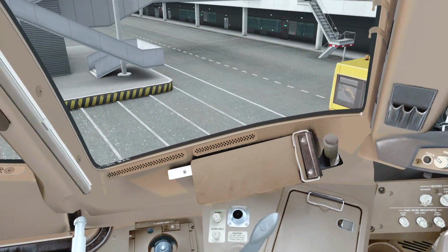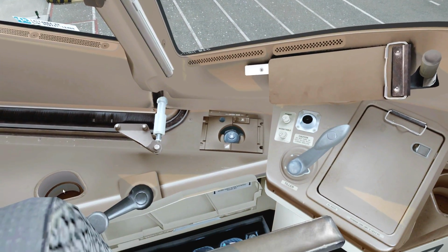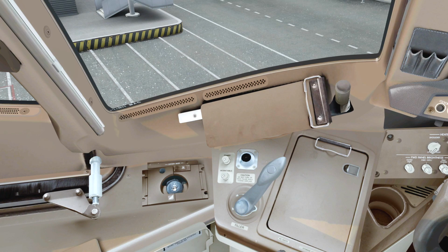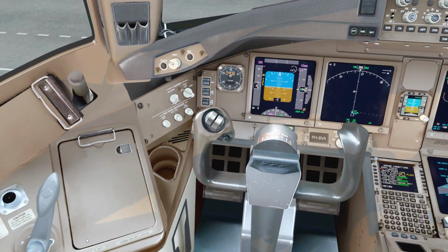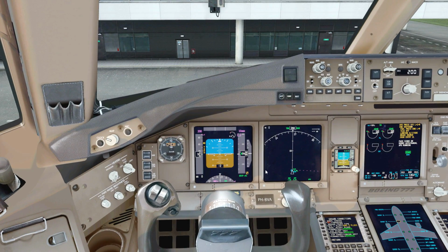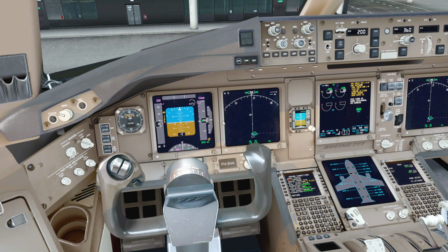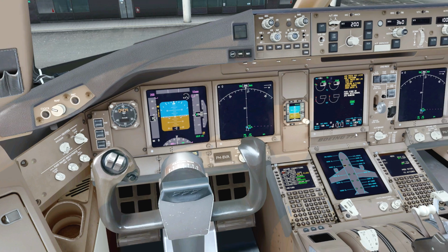So further going through the cockpit, you basically just want to check that the windows are closed. You can do a little test of the oxygen mask right here, make sure it's working and it's stowed. And yeah, this is all airline specific stuff. You just want to make sure that all the emergency systems are in place and working. Here we have the display light switch. You can just adjust them to your liking again. Of course it's now daylight, so it doesn't really make sense to adjust these knobs. Just give a quick look at the displays, make sure everything is fine.